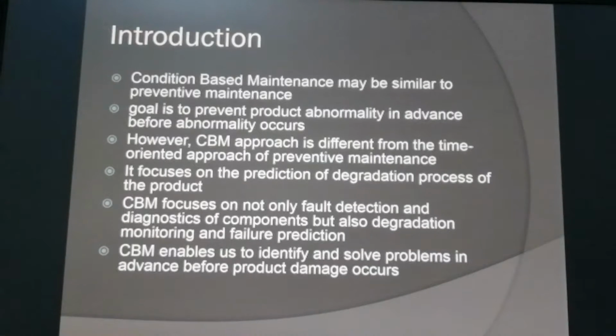Introduction. Condition-based maintenance may be similar to preventive maintenance. Its goal is to prevent product abnormality in advance before abnormality occurs. However, the CBM approach is different from the time-oriented approach of preventive maintenance. It focuses on the prediction of the degradation process of the product. CBM focuses on not only fault detection and diagnostics of components but also degradation monitoring and failure prediction. CBM enables us to identify and solve problems in advance before product damage occurs.